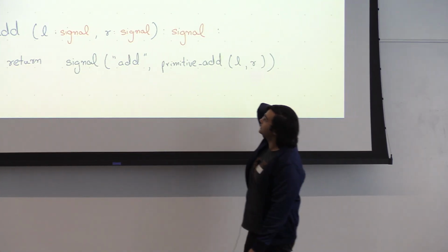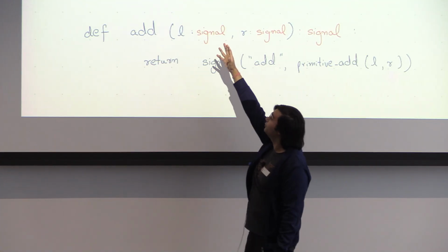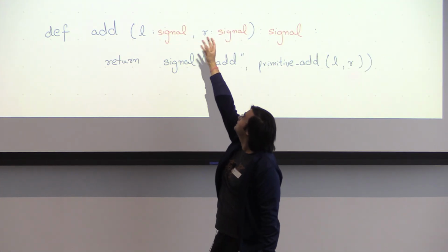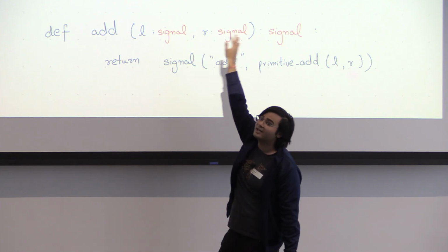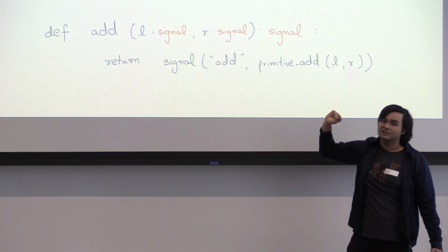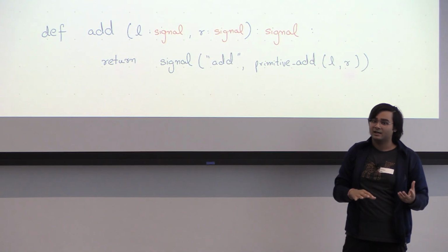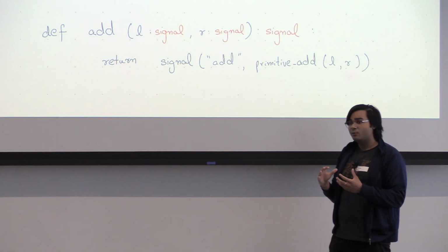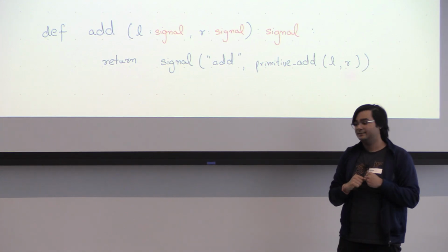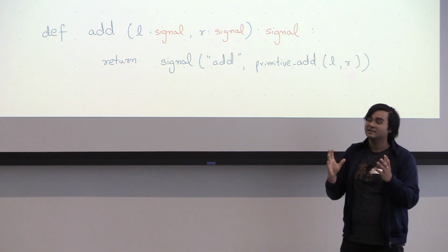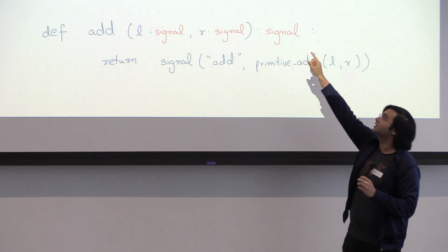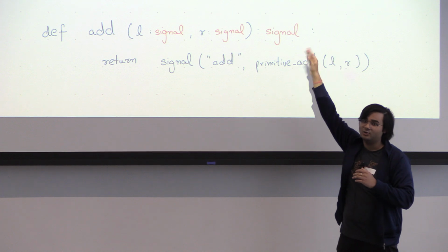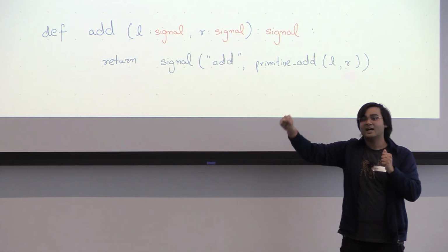The problem is, it's not really a problem, but the way we build this embedding, the HDL language, is everything on the right side of that equal sign. Clock is just the name in the host language. For example, the way this works in Hardcaml, we have basically a preprocessor pass that allows you to do exactly what you're thinking about, which is you say clock equals signal wire with no clock in it, and it'll copy that name for you.